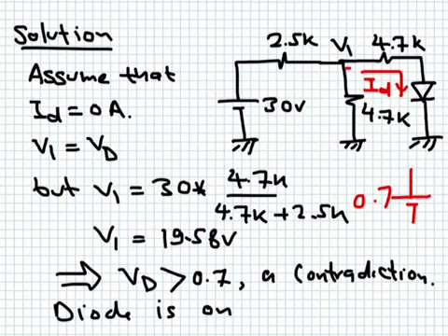Okay, so once the diode is on, it represents between the anode and the cathode a drop of 0.7. So between this terminal and this terminal, you have a drop of 0.7. You can replace it in your calculations by a battery of value 0.7 and try to determine the current that's being sunk into that battery. This battery will not supply current; it will actually sink current. So the current in this battery will flow in this direction, from the anode to the cathode. So let's see how we can analyze this circuit using the techniques that we learned before in circuit analysis.